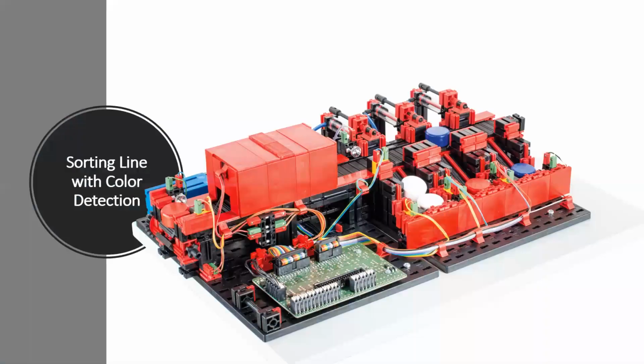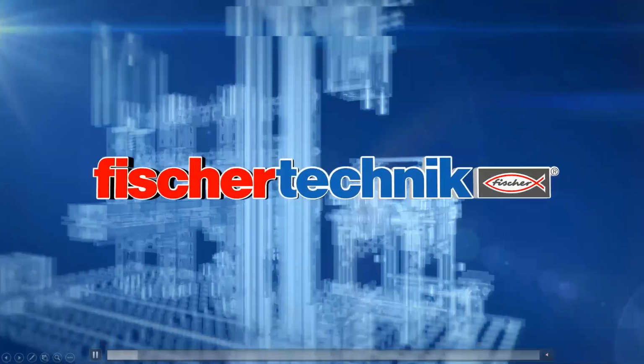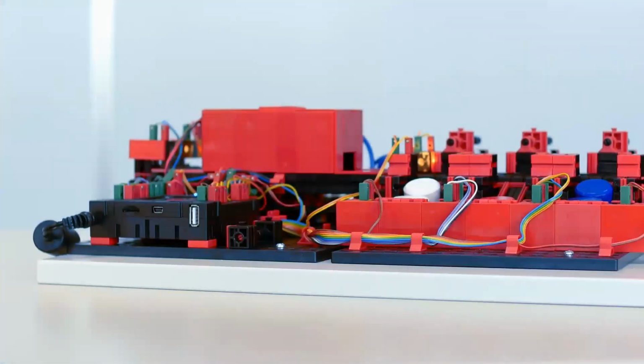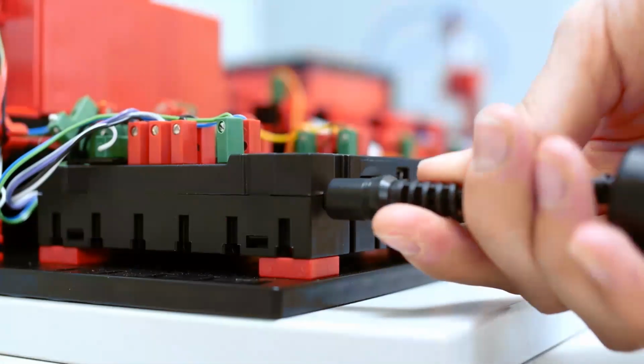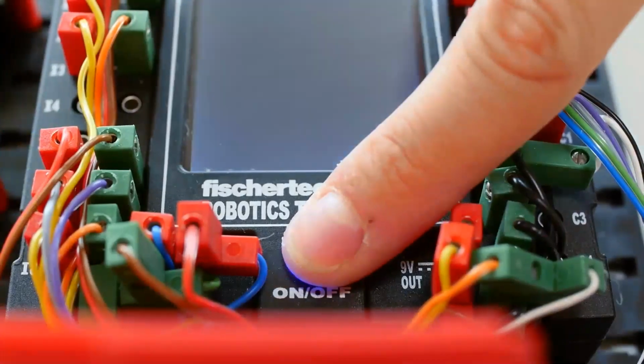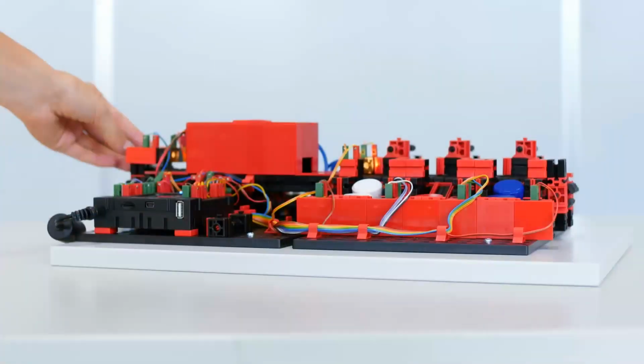And there you go. The next model in our progression is the sorting line with color detection. Now this simulation, without the sound, features a system for detecting workpieces of different colors, and it sorts them via a conveyor belt into 3 different storage bins. Components on this model include 2 mini motors, 5 phototransistors, 5 LED light barriers, 3 solenoid valves, a compressor, and an optical color sensor.